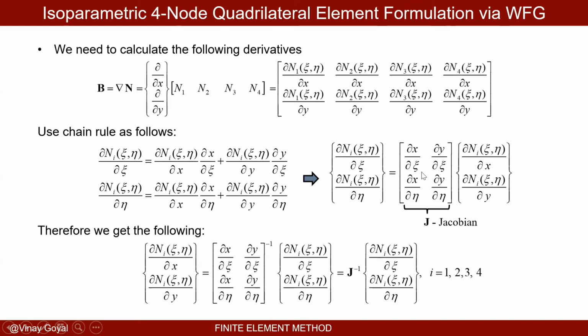And that's the one that gives you the mapping. We've been able to decouple it somehow from having to approximate the temperature over the domain, because now the temperature is only approximated over the square domain. I don't have to worry about anything else except to calculate this Jacobian, which I'll show later.